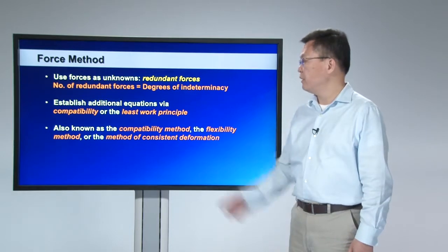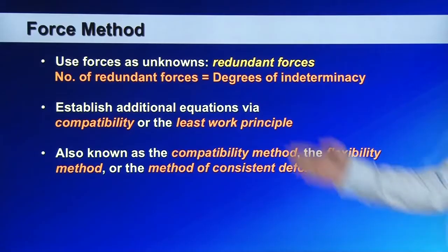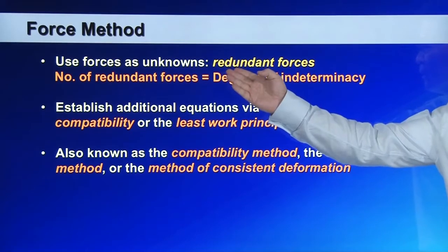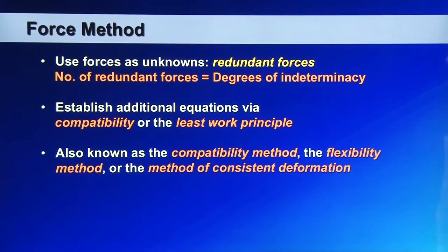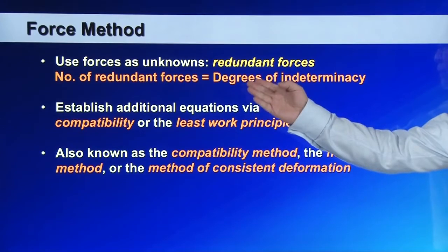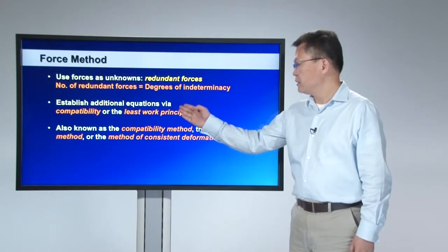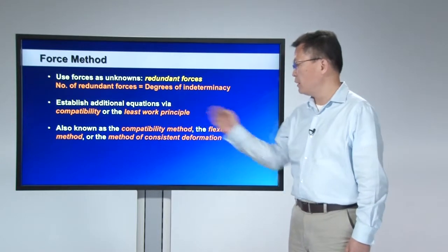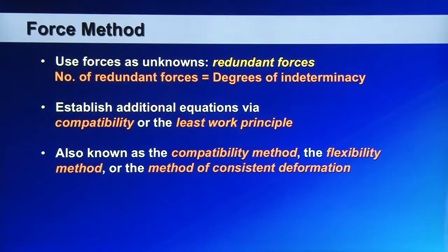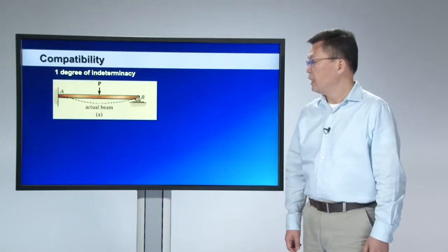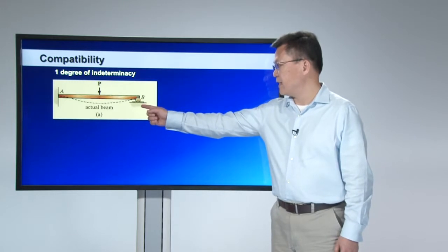I'm going to introduce the force method. The force method uses forces as unknowns, called redundant forces. The number of redundant forces should be equal to the degree of indeterminacy of your structure. And we can establish additional equations through compatibility or least work principles. So the force method is also known as the compatibility method, the flexibility method, or the method of consistent deformation.